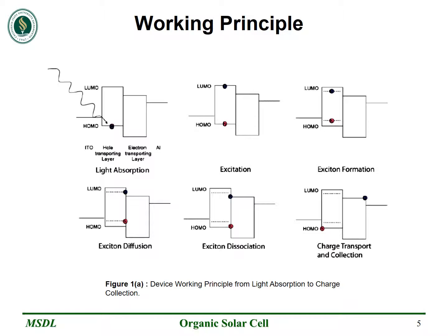After light absorption, organic semiconductors require additional processes to produce free carriers. First, semiconductors form excitons, which are strongly bound electron-hole pairs that then diffuse inside the organic semiconductor, independent of applied electric field. Exciton dissociation occurs only at the interface between the donor and the acceptor due to the offset of the HOMO states of the donor and the acceptor.